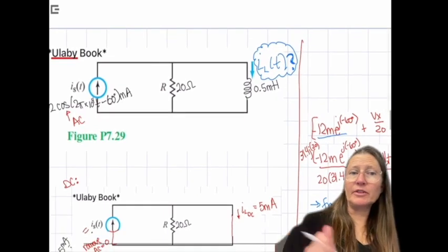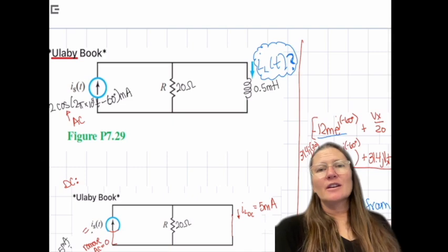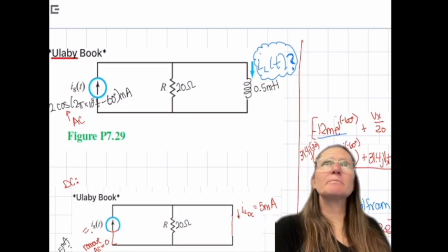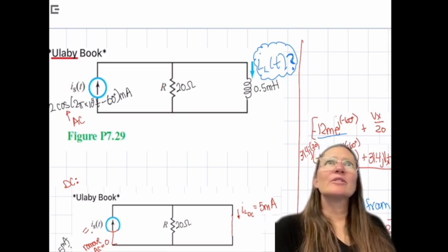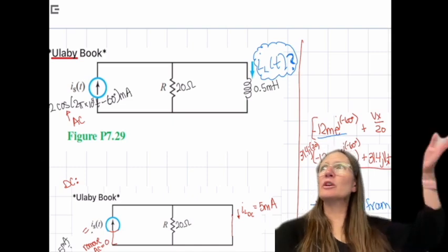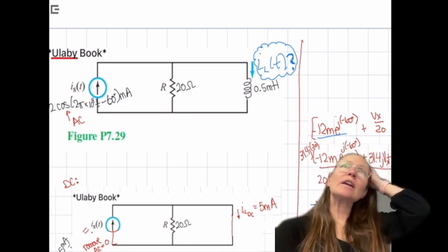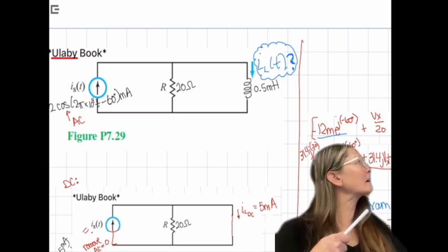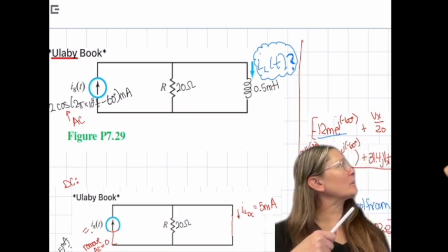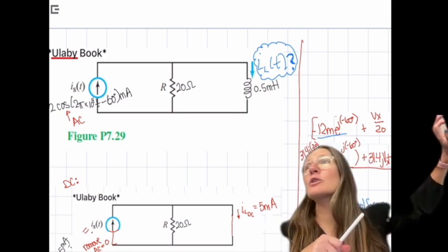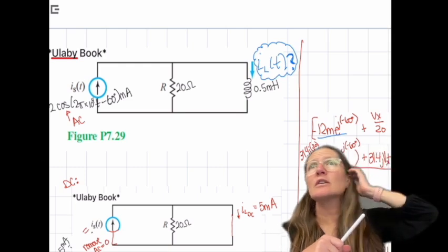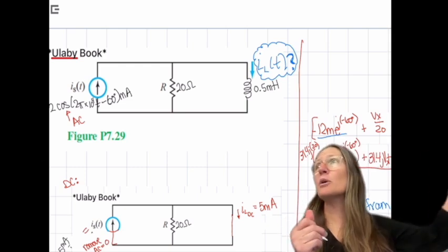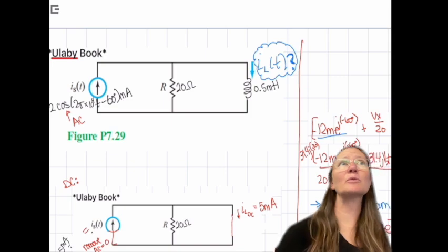So previously we looked at this with a switch and we only looked at DC, right? We looked at the DC with a switch going in there. So the AC portion of that is a step function. So you can actually go back and solve what we had done with the switch and instead put U of t for a signal going on there. And you can do the same method and come up with the same expression as we were getting before.